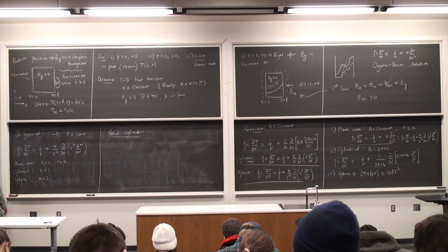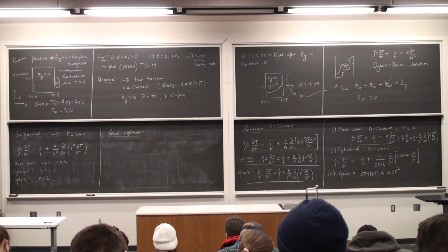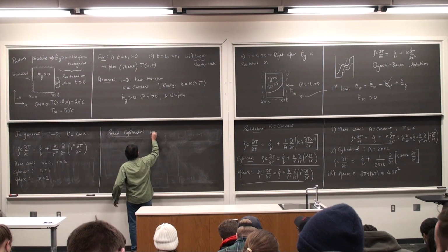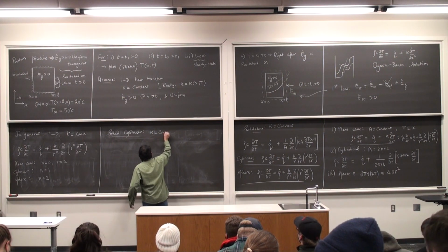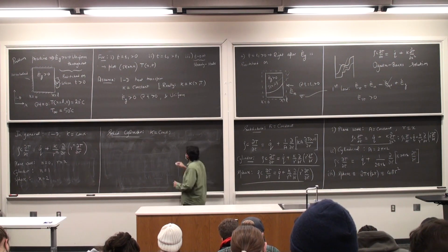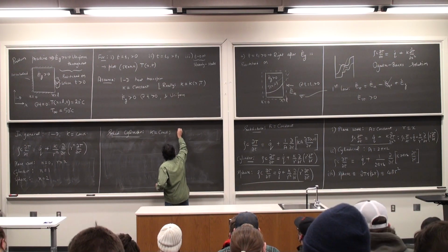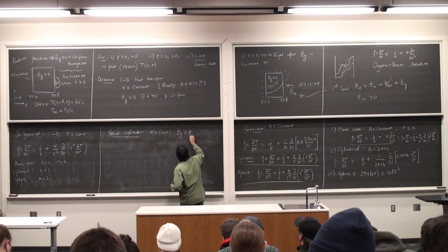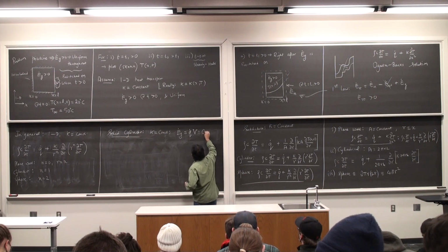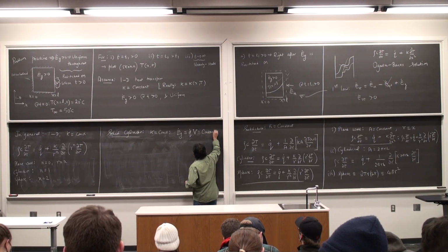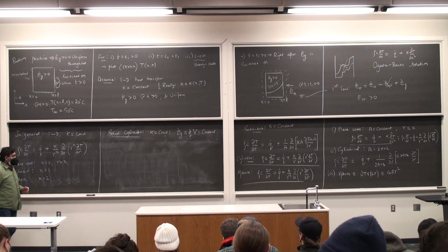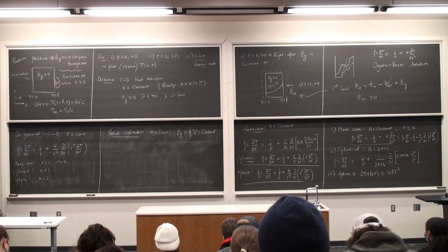How does heat transfer take place in a solid cylinder? Start with the heat diffusion equation, and I'm going to say k is constant. I'm going to look at a situation of constant volumetric energy generation. So E dot G, which is q dot times the volume, is a constant. It could be positive or negative, I don't know, but let us assume it to be constant. So q dot is constant.